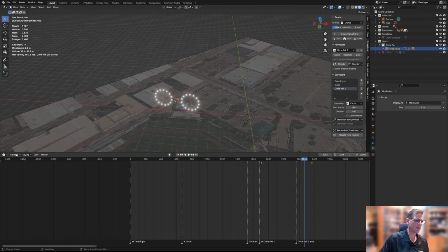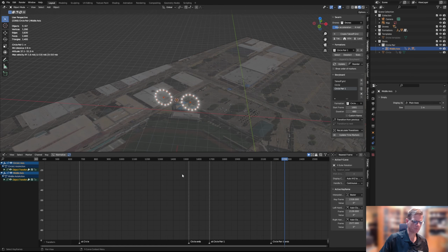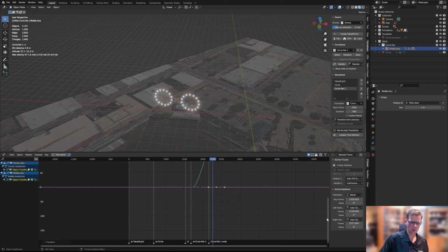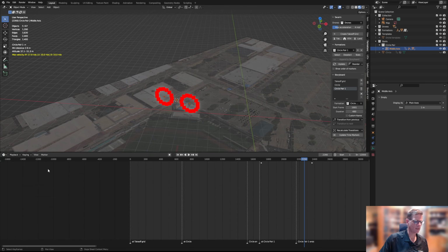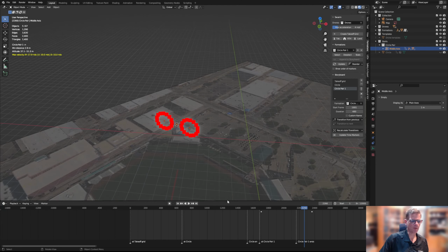You can definitely play with the graph editor there and smooth out some of that Bezier curve so that it takes less time. It's basically just like that. Like that, and that's going to get things in a little bit more uniform motion, so there's not so much acceleration in the middle. But I guess I said I wasn't going to do that in the interest of time, but I just did it, so it's done. And so now we see our max speed is only 2.3,